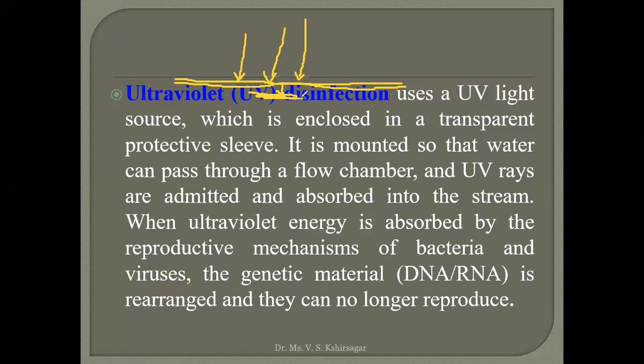But the additional advantage of ultraviolet radiation is not only killing the current bacteria, but also killing the fertility of that particular microorganism. Means there will be a direct impact upon the fertility or the genetic material of the microorganism, and hence there is no possibility of growth of microorganisms in that particular tank later on. But there is also a recontamination issue.